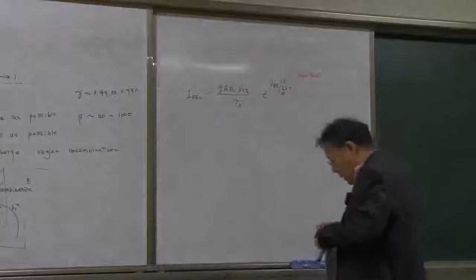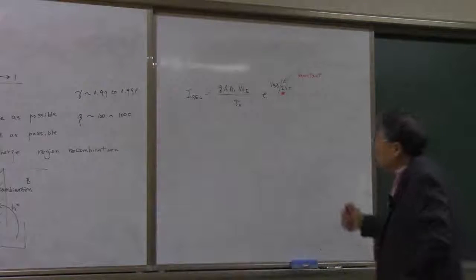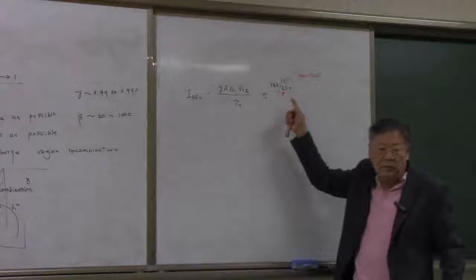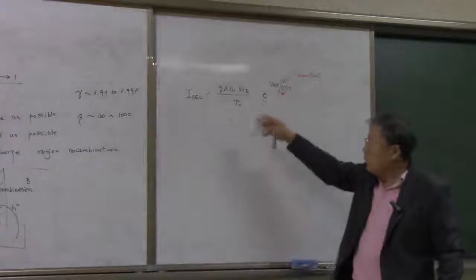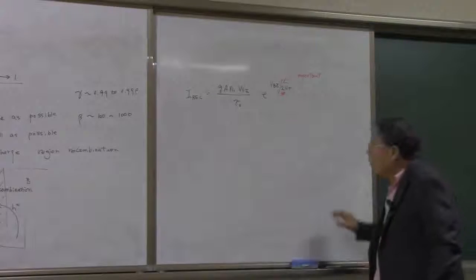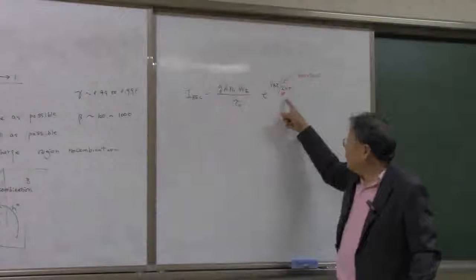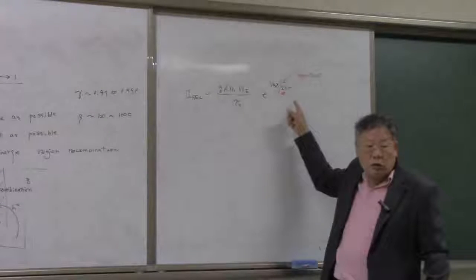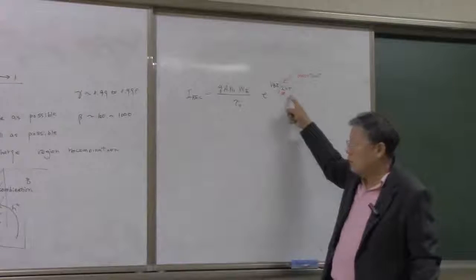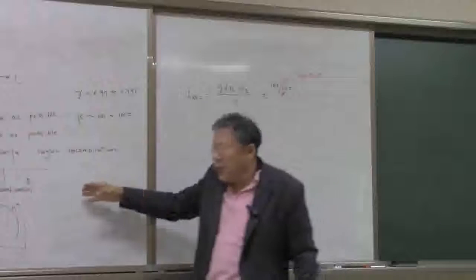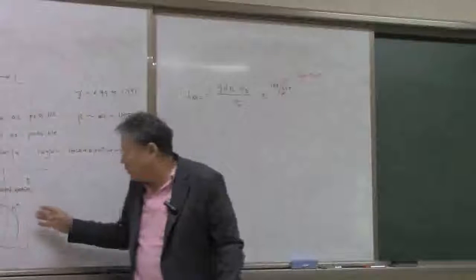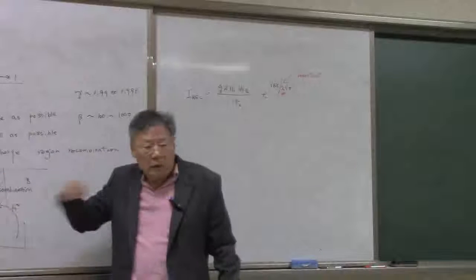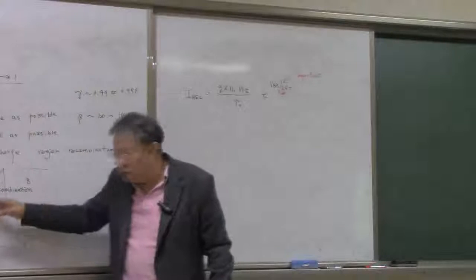Right? We usually do not have this 2 in front of a VT in the equations, but in this recombination, we come up with this factor 2 in front of the VT because recombination happens by the injected electrons and the holes injected to the base.